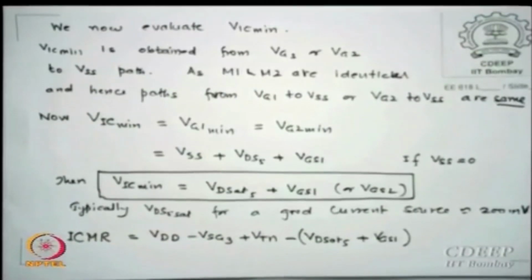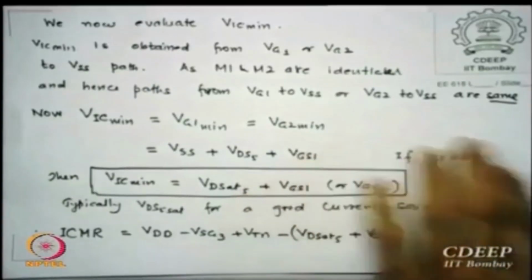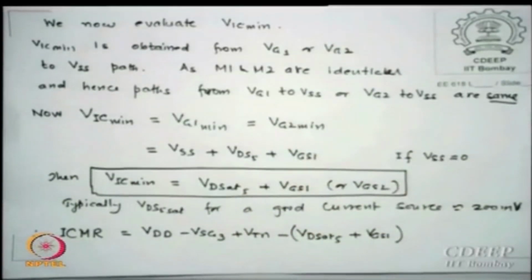Okay, is that point clear? This is a trick in designs, which spec is given and which you have to evaluate. Please remember VSS equal to 0 is not a normal case. In most op amps you will always have dual rail, so you will have VDD 2.5 and VSS minus 2.5, swing still may be 5.